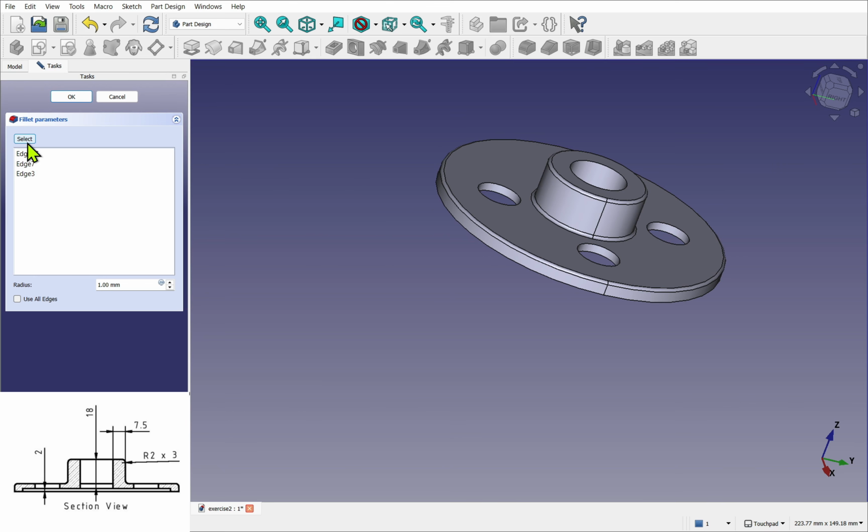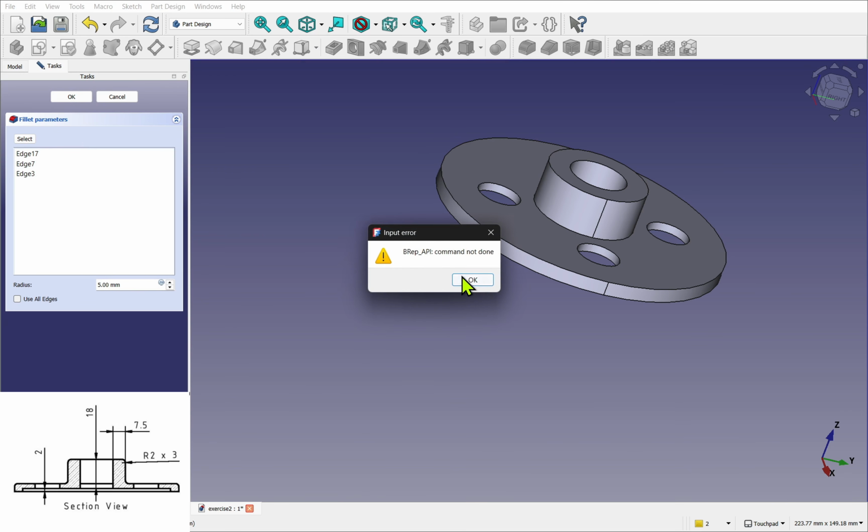Now, one thing with this, I'm going to go back into Preview mode. If I change the radius, we can see we get a preview. If this radius grows so it's larger than the edge that it crosses, you can see it's 5mm here, then the fillet will fail. You can see no fillets added. If I hit OK, it comes up an error.